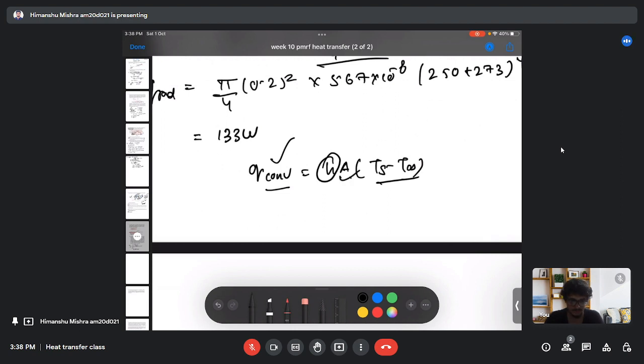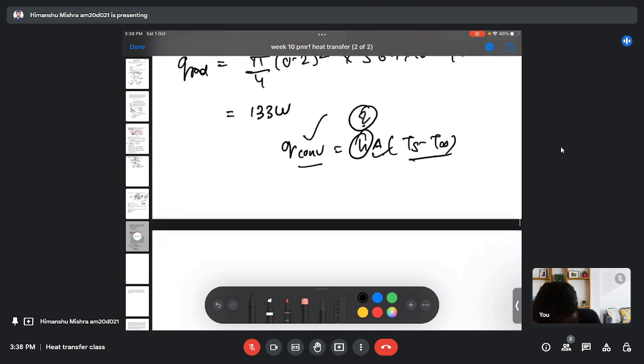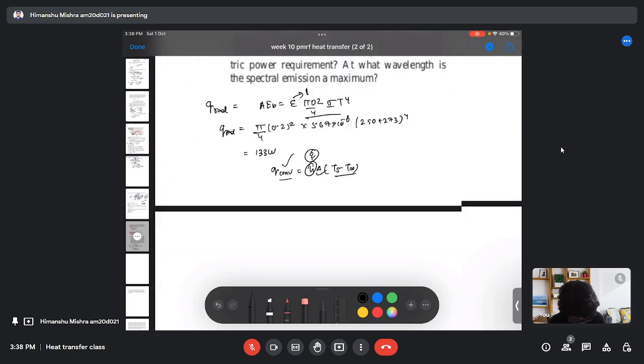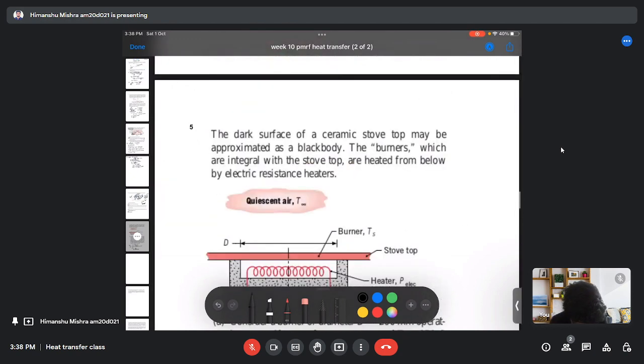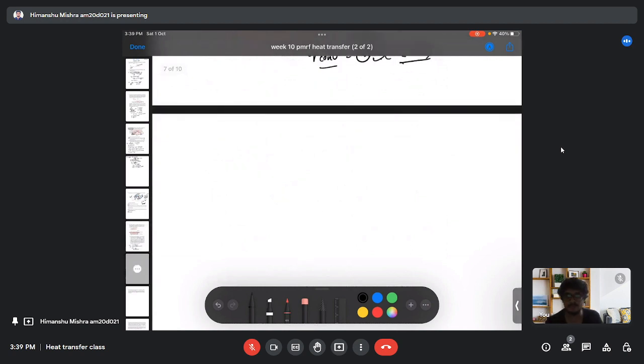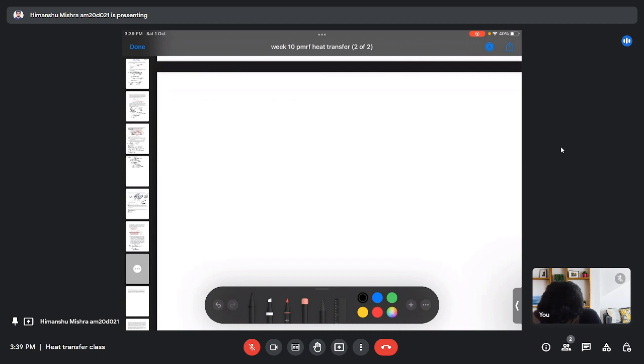We have the area, but we need to find this heat transfer coefficient, and to find it I am using the Nusselt number correlation. Since it is not given in the question that there is motion of air because of a pump or some other external means, I will assume this heat transfer is due to natural convection.